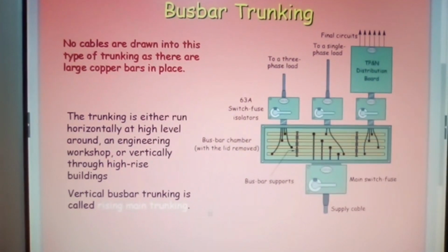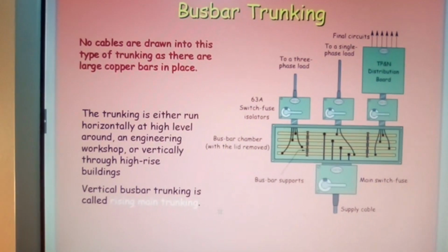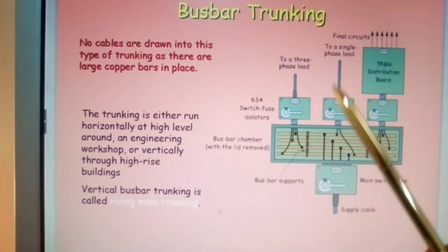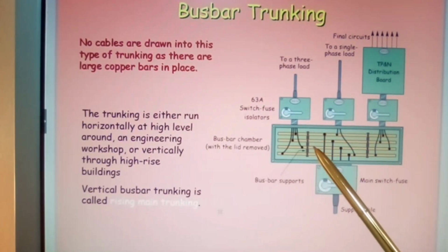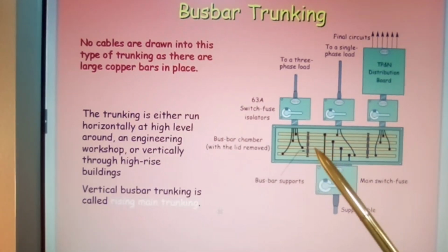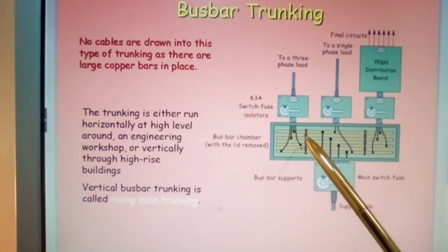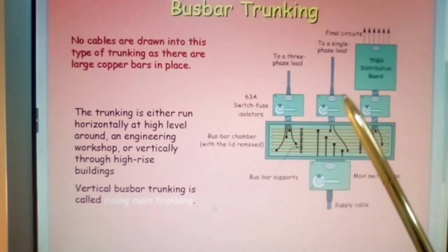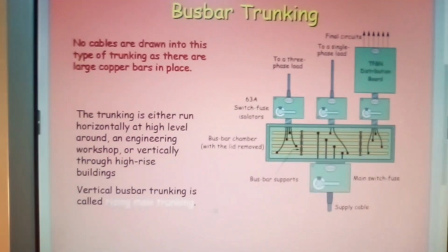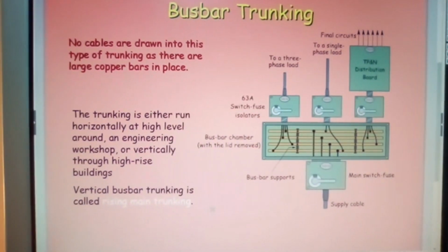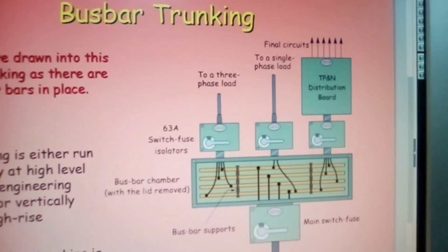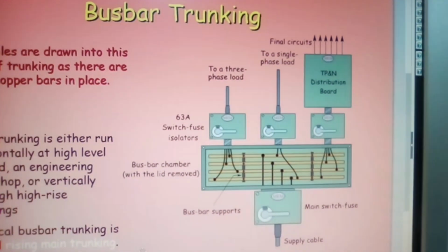Now here we have a distribution unit system. And what we're looking at here is the bus bars, 1, 2, 3, 4 bus bars. Now why 4 bus bars? Because you have 3-phase and a neutral. That still carries your neutral bus bar system, and that's what you need to bear in mind, it still stands. So let's just go in a little bit, make sure that you can see and read everything that has been said.